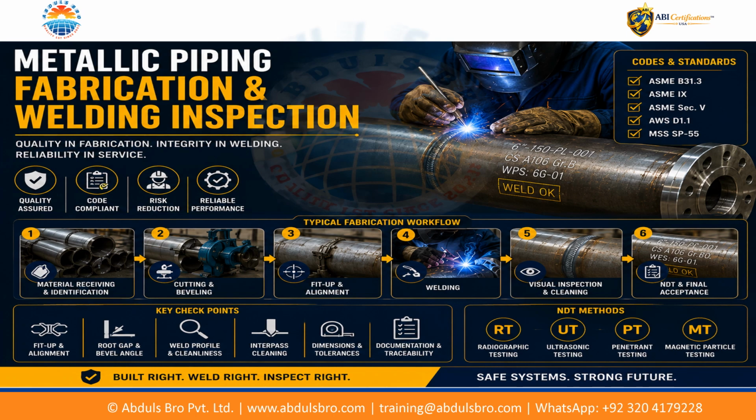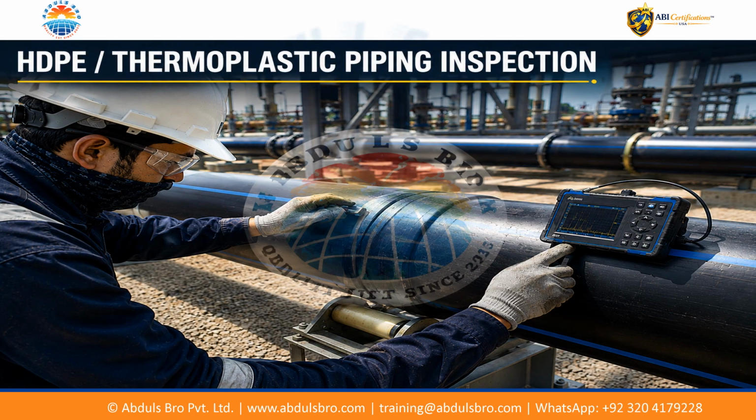is released for installation. HDPE and thermoplastic piping requires controlled fusion and jointing processes rather than conventional welding inspection. QA/QC verifies material identification, compatibility, joint preparation, cleanliness, alignment, and the applicable pre-qualified jointing procedure. Butt fusion and electrofusion joints are performed using qualified procedures, personnel, and suitable equipment, with specific fusion parameters controlled and recorded. Completed joints are visually examined for acceptance, workmanship, and traceability before installation, restraints, and subsequent testing in accordance with